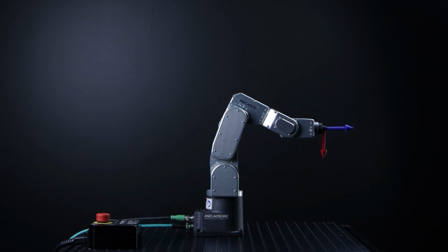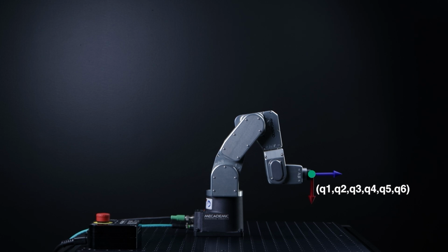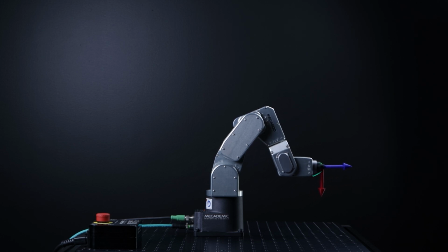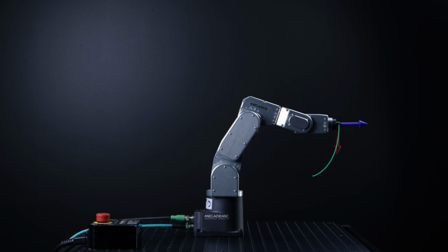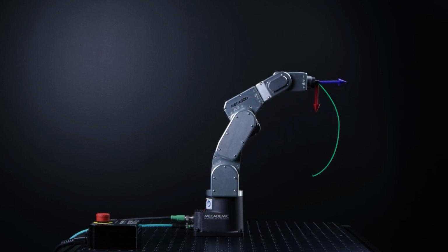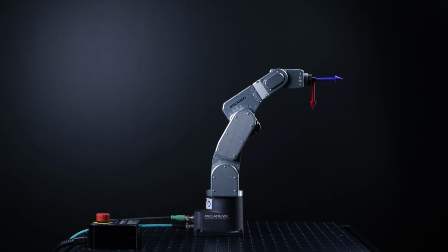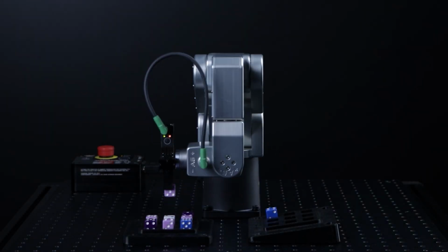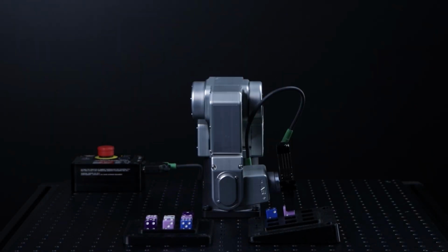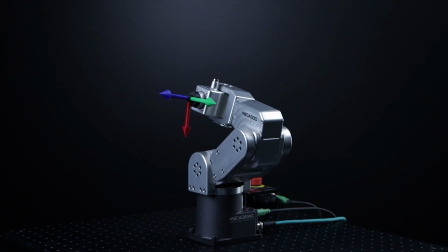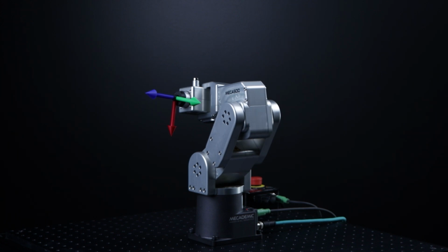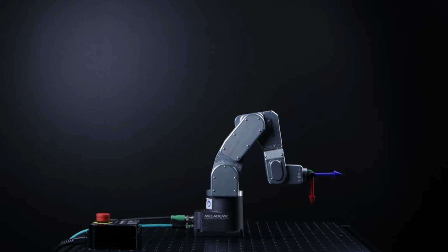For joint movements, you specify the desired joint positions directly. You control the robot in joint mode or, as we often say, in joint space, when you don't care about the precise path of the robot end effector. For example, you move the robot in joint mode when you want to move from a retreat position to an approach position, far from obstacles. You also move the robot in joint mode to a given set of joint positions, which may correspond to a singularity. However, you often need to specify the position and orientation of your robot's end effector directly.